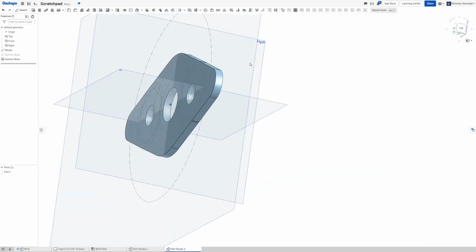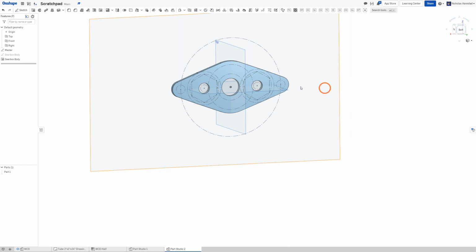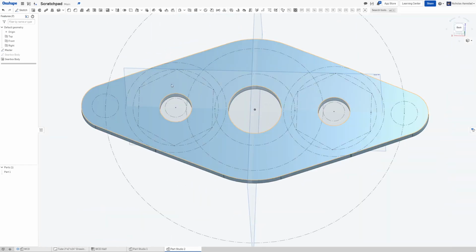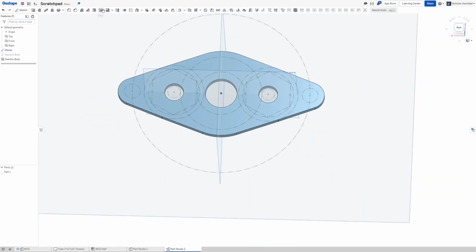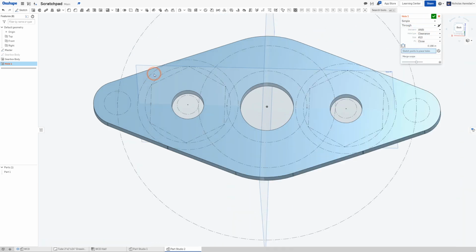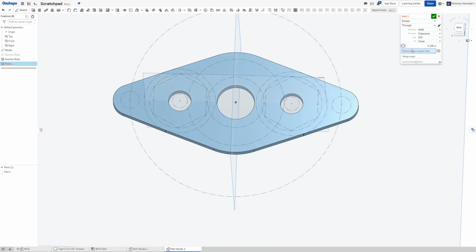Doing it this way also gives us some benefits. So now we can just use those points directly for our holes. Just not make that a countersink. And those are probably number 10 holes. And then let's see how Onshape feels about me just giving it that. It's not a fan. So we'll select them manually.